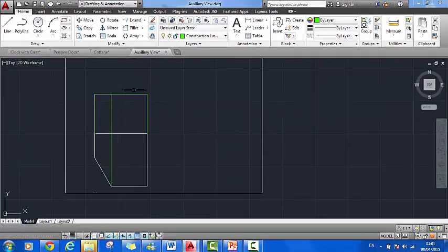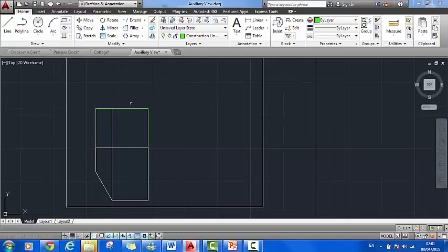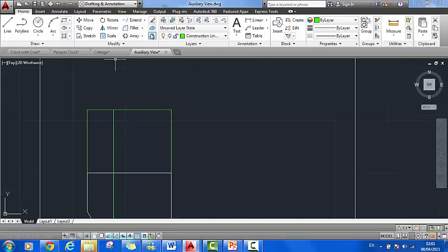Now, earlier I referred to orange rectangles that were acting as finger joints. These were to accept 3mm clear perspex. So just temporarily, I'm going to offset this XY line 3mm. I'm going to offset that line 50mm high for the height of my actual object.